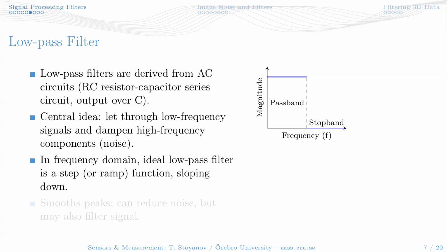And from here on, it is the stop band, so we have 0. And this is the frequency domain representation of the filter, right? This is not the time domain representation. So we take the frequency domain version of the signal and we multiply it with this, then we would get the filtered signal.